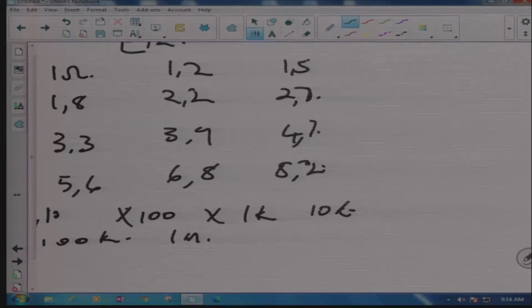So this is how we go about it when we work with resistors and we want to know their E12 range. Let's make a hypothetical example here. If your answer was 3.7, which one would you use? Obviously, you use the next higher one, which is 3.9. And you redo your calculation to know exactly what the current and other parameters are.